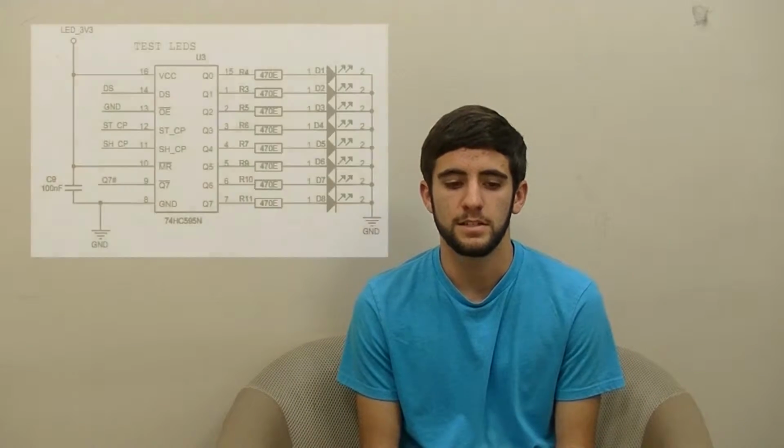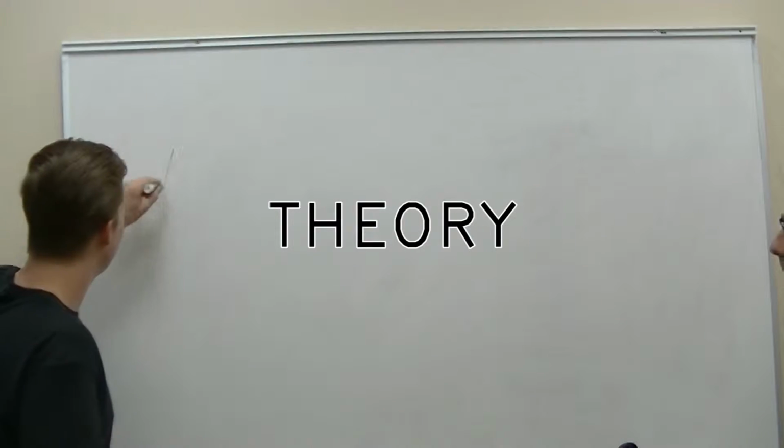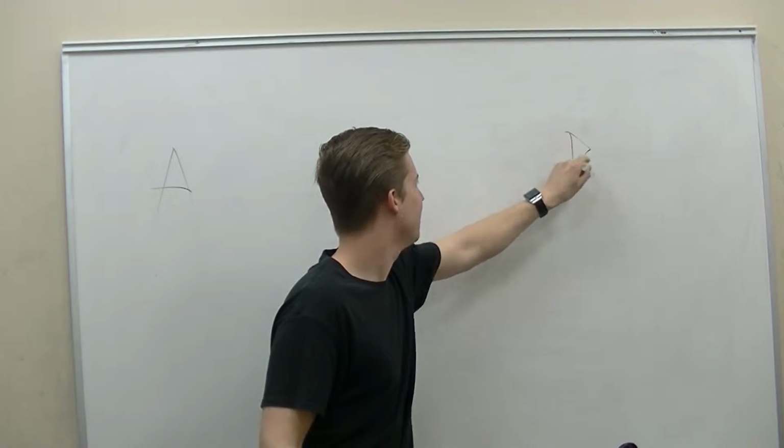The objective of our lab is to use a shift register and a microcontroller to transmit data. Then we're going to compare that data and send it through parasitics using capacitors and inductors. Using the data and the circuit we created, we're going to create an eye diagram and calculate the bit error rate. And then at the end, we're going to discuss a recovery method to try to reverse all the parasitic effects.